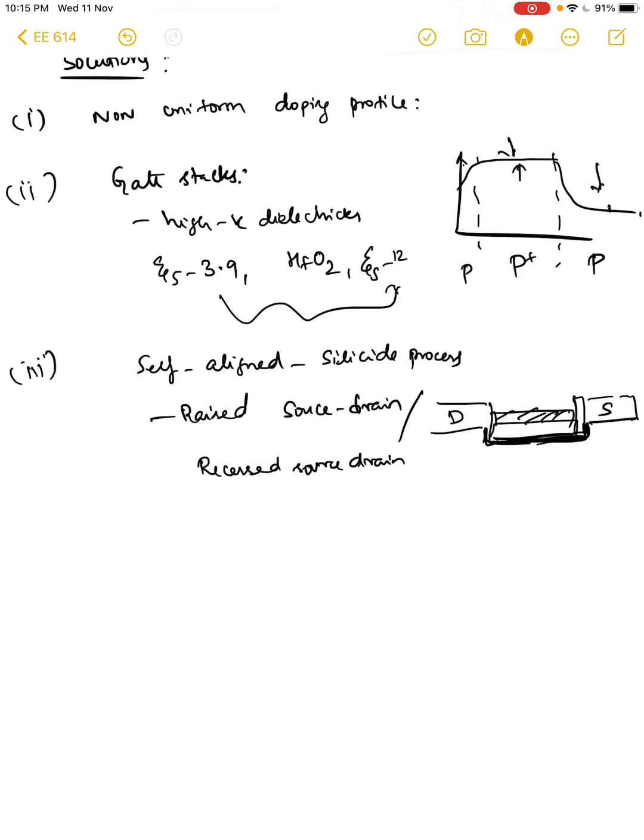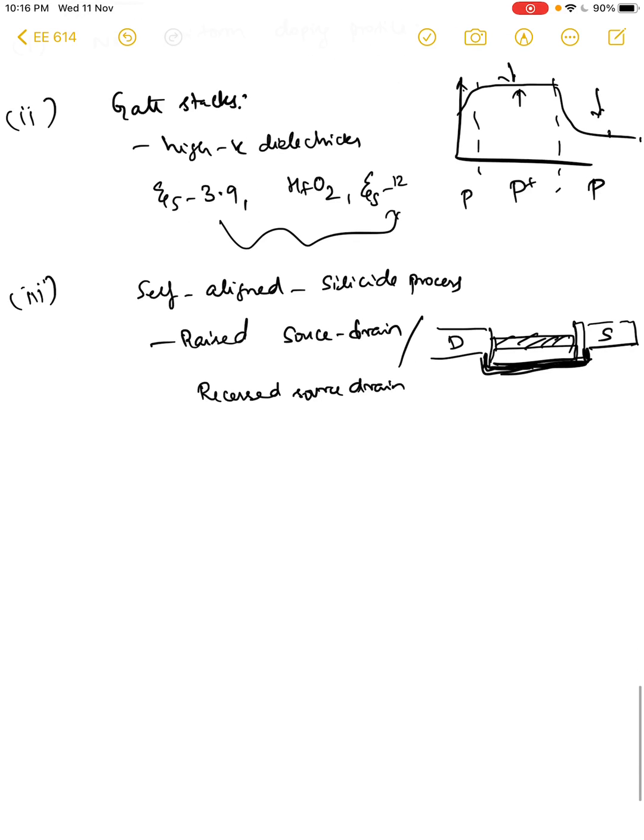So here you see that you have effectively avoided the source drain pinch off, source drain charge sharing, source drain punch through, right, and subsurface punch through, and all such effects. But then you have other issues with the gate field not being uniform across the channel, because the channel is now not a straight line but has to go through all sorts of inhomogeneities that we have here, right? So this is called a recessed source drain or raised source drain design.